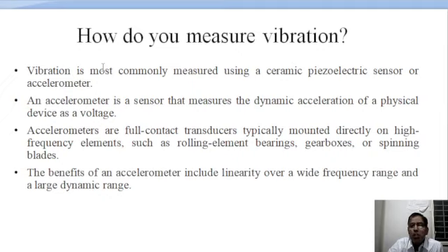Accelerometers are full contact transducers typically mounted directly on the high frequency elements such as rolling element bearings, gearboxes or spinning blades. So these piezoelectric accelerometers are contact type accelerometers, wherein the accelerometer has to be kept in contact with the surface whose vibration we are measuring.